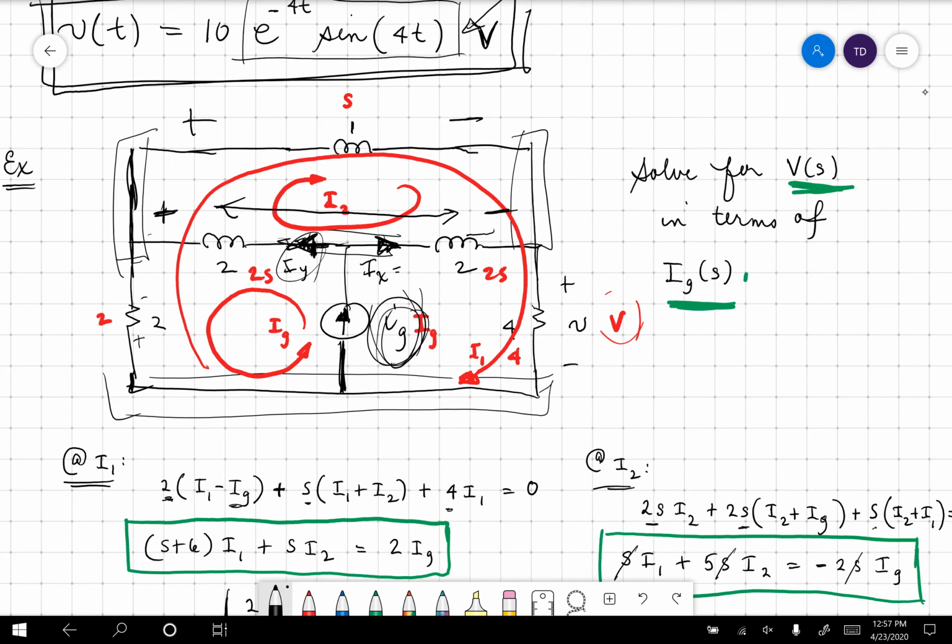If I change the location and put one of those inductors over here, that would not be the case. So it started off looking like it could be a really challenging problem, but in fact, this is a, quote, first order circuit, even though there are 3 storage elements. That means if we looked at this in other ways, and we're not going to do that today, we could actually reduce this to a single storage element. So like if we did a Thevenin equivalent, we could reduce it to a single storage element. Pretty interesting.